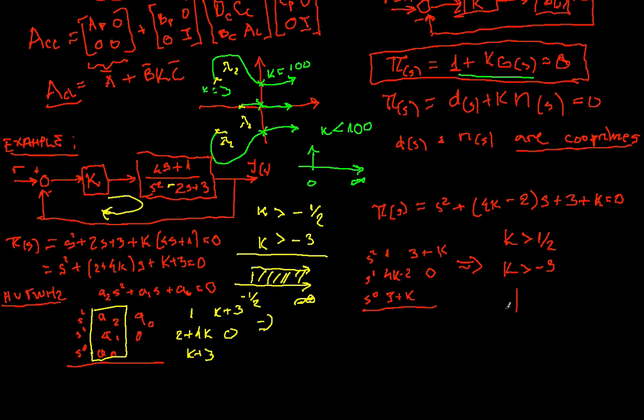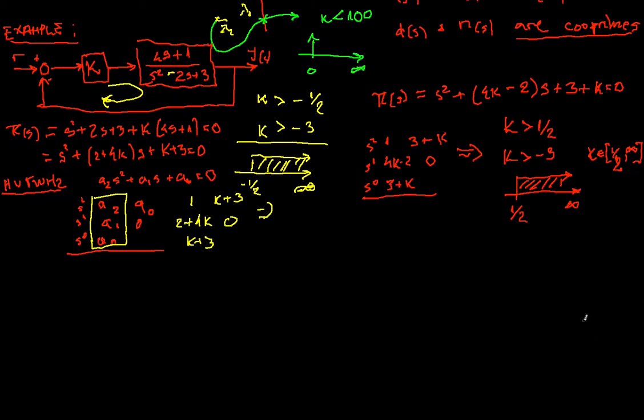As you can see, the range of the available gains that can stabilize the closed loop system in the case when the original system is unstable is already smaller than in the previous example. So here k is going to be all values from 1 by half to infinity. So the gain, still pure gain, from 1 by half to infinity. Okay. Interestingly enough, we are still dealing with a simple gain.